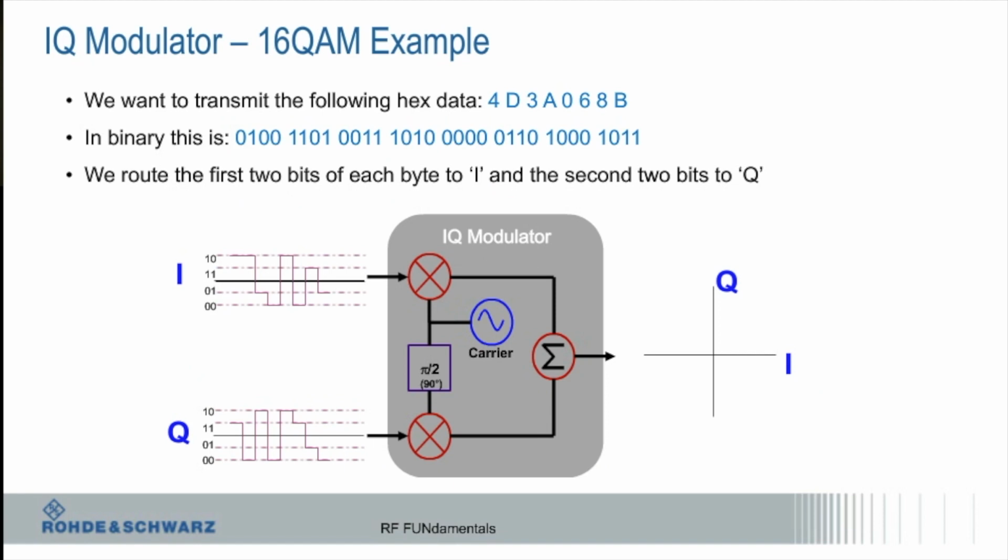So if I look at that IQ modulator example, obviously when you make this stuff, there's a lot of other stuff back here that is behind the curtain for me. I'm an RF guy. But you would have to take your bit stream and make it into a multi-amplitude signal, probably from a D to A, and generate this and then split the bit stream, which would then feed the IQ modulator. And then this gets sent out somewhere.